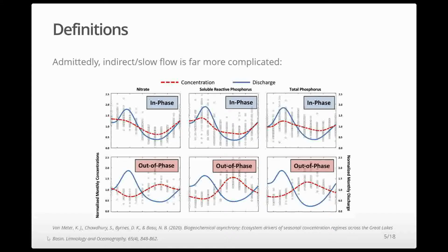And this could be attributed to other slow flow phenomena, such as superficial storage, like wetlands or stormwater management facilities, or infiltration into urban infrastructure, some call urban karst. And I take this to be a bit of a shallow water phenomena. And here we're going to neglect the seasonal shallow water phenomena and really hone in on the deeper system, long-term average phenomena.